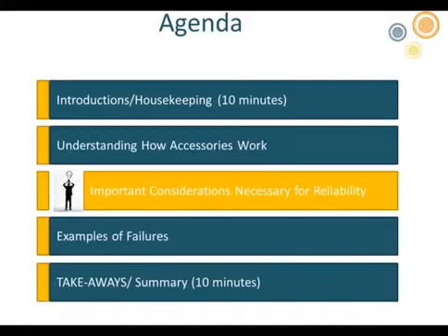Yes, and I'm probably partially prejudiced, but high K or high dielectric stress control terminations are pretty much dominating the market now. Almost everybody uses those, and it's for some of the things that I mentioned, because you have a lower surface stress, and if you have a lower surface stress, you're going to have less chance for tracking on the outside of the termination, and therefore you get more reliable, longer-term performance out of the termination. So based on the better stress control that you get with high dielectric stress control, I think it makes for a better termination